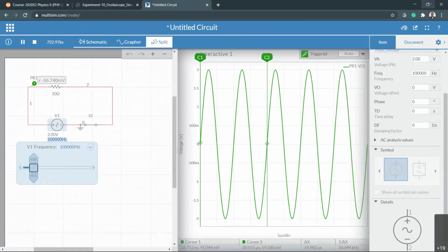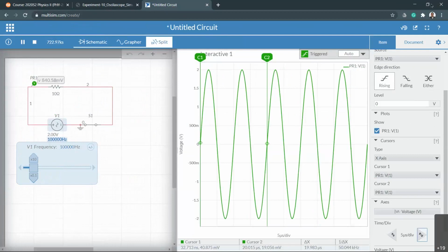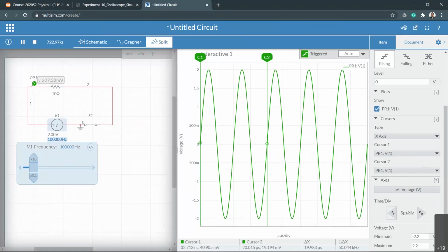Hit enter, then change the x-axis values, and make sure those are changing and this number is updating. You have to check both, otherwise our reading value right here will not be accurate, because the simulator has a little delay in updating these axis units. Please take a look. The axis unit should match the time per division value on your right hand operating panel. Then we are fine.